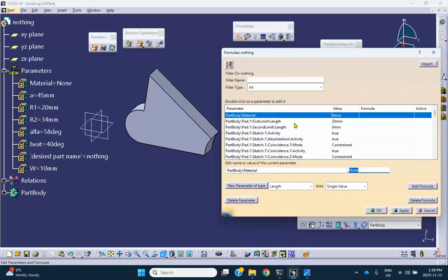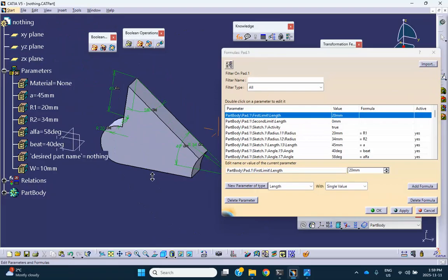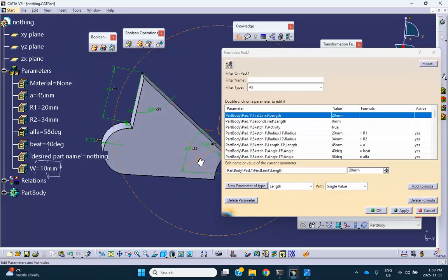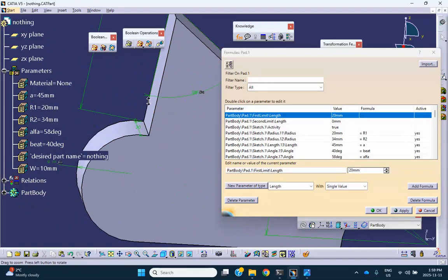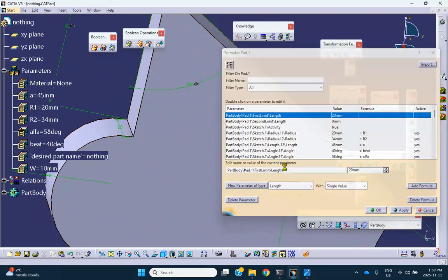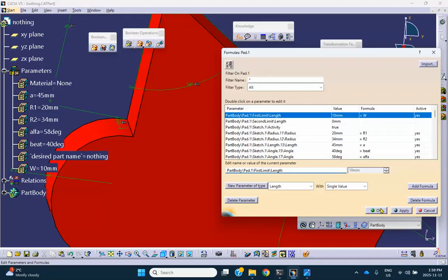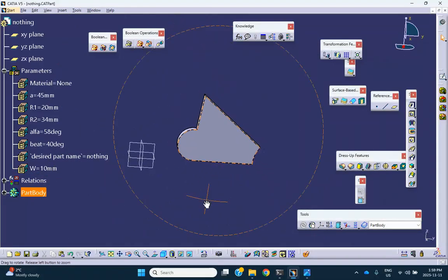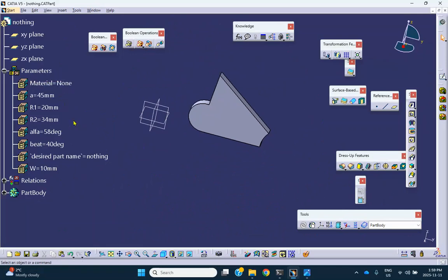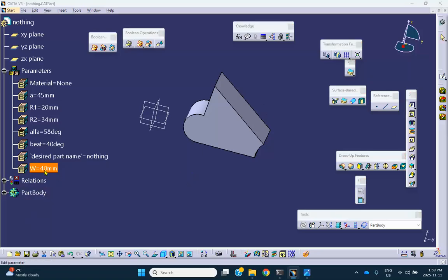So f of x. Click on there. Find where the pad length is, pad width is. It's right there. I can see that. There. The formula equal to W, and then we say OK. The only thing I haven't done here, let's go and check a few things. You haven't done anything about material yet. I know that. So first of all, let's go and check W. Let's make this thing 50 or 40, see what happens. Fatter. Let me put it back right once.